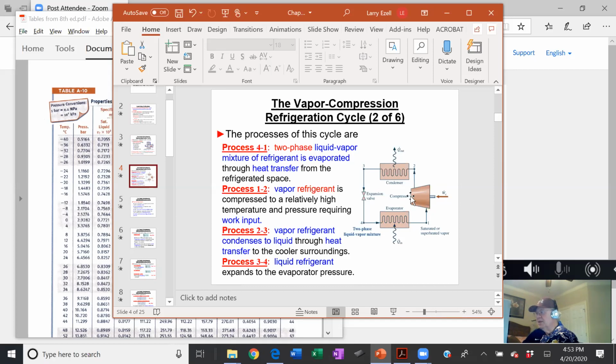And you do that with a switching valve. The compressor doesn't change rotation or anything, but a switching valve will now port the high pressure Freon through the coil that's inside. These coils are pretty much identical. So now the hot refrigerant is flowing through here and giving you heat, going through the expansion valve. The expansion valve doesn't care which way the refrigerant flows through it. It does its thing regardless. Now you go into the evaporator and you discharge the heat out to the environment. But what's nice about the heat pump, you're now using both the heat that you pulled in.